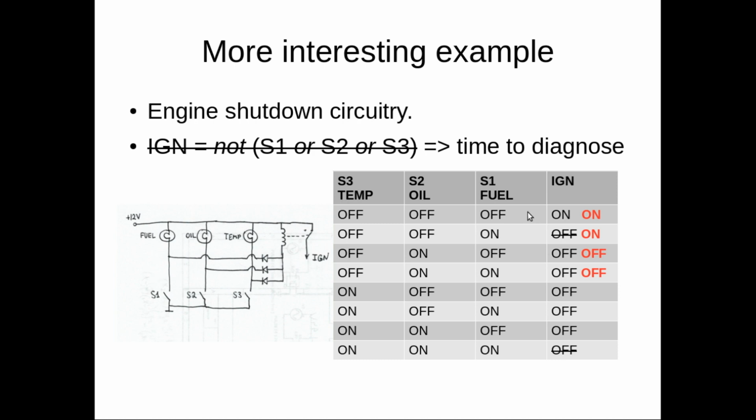So what happened is that we constructed this truth table from the wiring diagram. We observed what actually happens, so we reconstructed partially the observed truth table, and based on the differences we focused on what's important, which immediately gave us direction for our diagnosis. Now, with this information, we can go with our test lights and see if these wires are good, check the integrity of the diode, and complete our diagnosis.